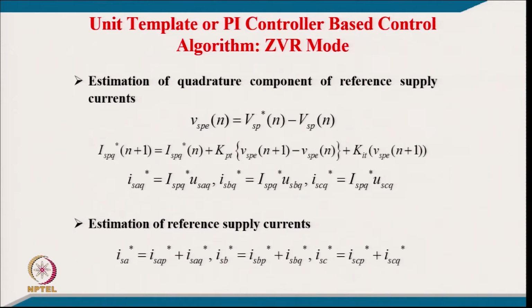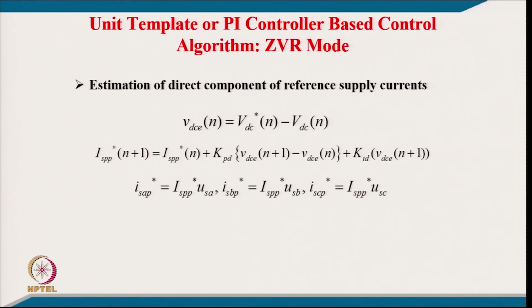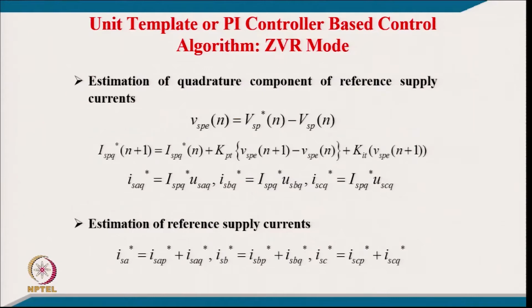Sometimes, as I was mentioning earlier, for the in-phase component for DC link voltage control, we normally keep showing a PI controller for both, but here we can use the sliding mode controller. There may be a small steady state error in DC link voltage, but that is the internal structure of the D-STATCOM. But the AC voltage controller should be a PI controller, because a PI controller has zero steady state error, and you would like to regulate the load voltage at the point of common coupling because it is fed to the load.